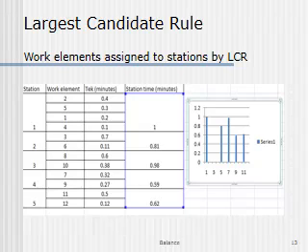Based on that cycle time, we couple two or three operations in one station, and on this station we perform those operations. If the cycle time of 1 minute is not obtained, we choose another station. This figure shows the 12 operations separated into 5 stations, with the time of each operation given.